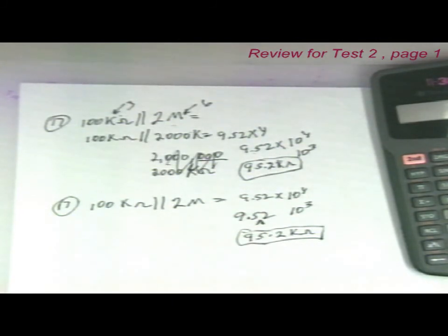Okay, the current through any branch of a parallel circuit is inversely proportional to the branch resistance. Now stop and think what that actually means. The current through any branch of a parallel circuit is inversely proportional to the branch resistance. Does that make sense to you?